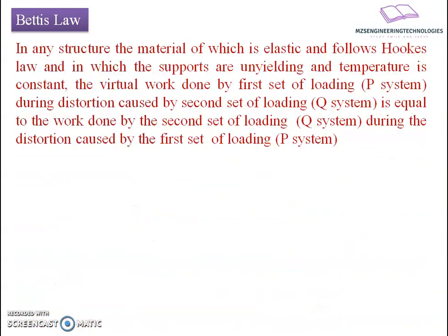This was extended further by Betti, giving an extension towards a set of loadings. The statement says that in any structure, the material of which is elastic and follows Hooke's law, and in which the supports are unyielding and the temperature is constant, the virtual work done by the first set of loading, the P system, during the distortion caused by the second set of loading, the Q system, is equal to the work done by the set of loading Q system during the distortion caused by the first set of loading P system.